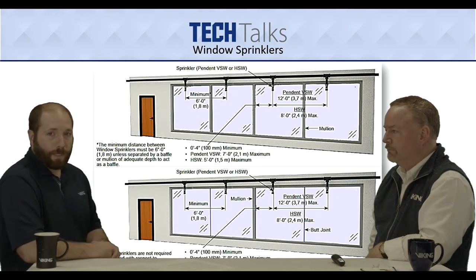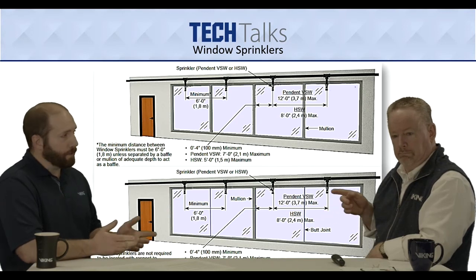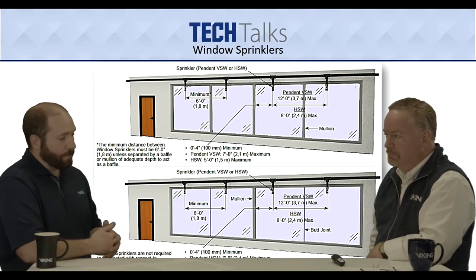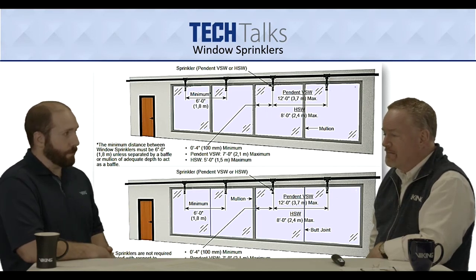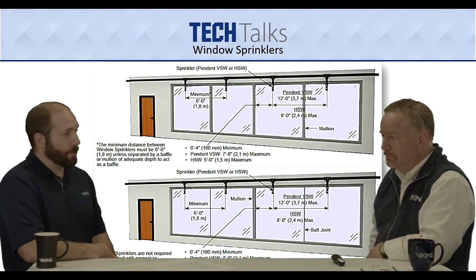If we notice, closer towards Jim, we've got the pendant vertical sidewall, and it's showing the spacing. The spacing for the vertical sidewall is 12 foot. So you can space them out 12 foot between the sprinklers, which is a key advantage. Prior sprinklers, the spacing was 8 foot, just like our horizontal sidewall installation shown there, which is still an 8 foot max.